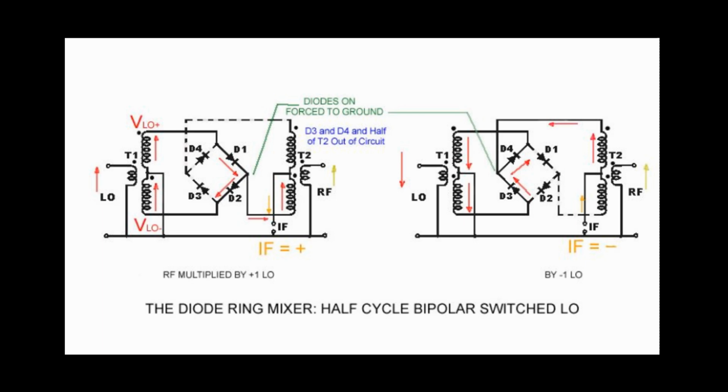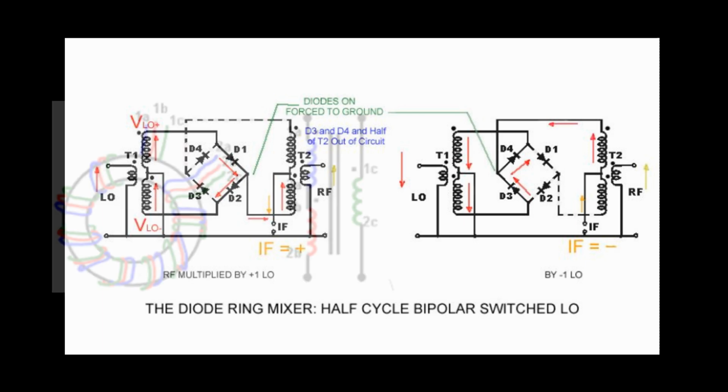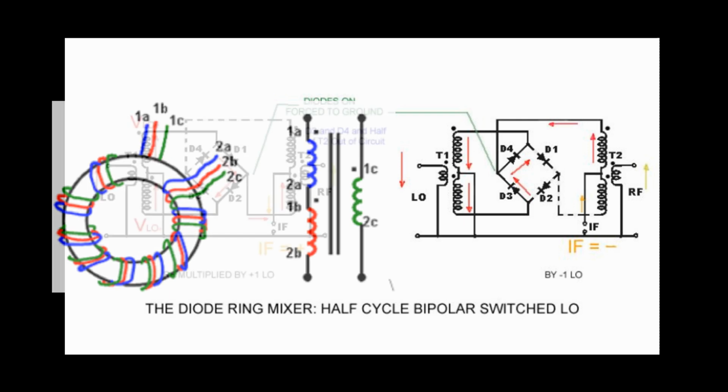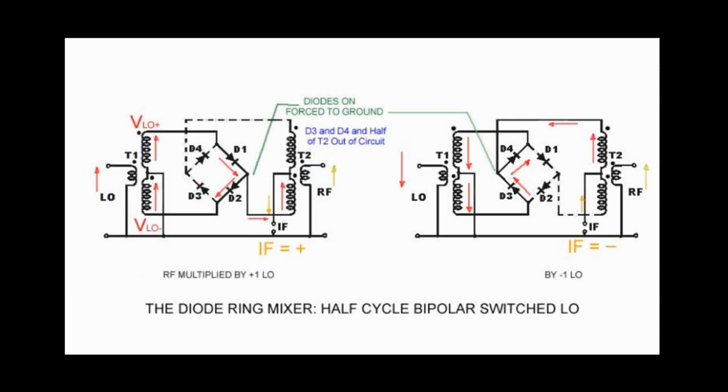T1. Let's say we make T1 as a trifilar transformer with all the windings the same on a toroid. What would the output impedance be? It would basically be a 4-to-1 transformer. Considering 3 equivalent windings, we have a 2-to-1 ratio, which will produce a 4-to-1 impedance step up.